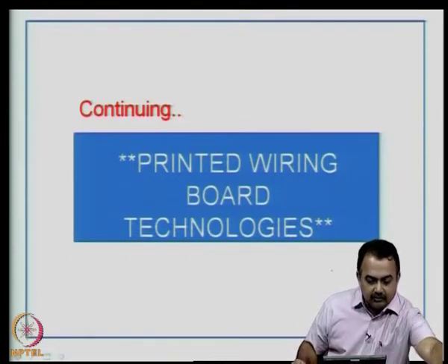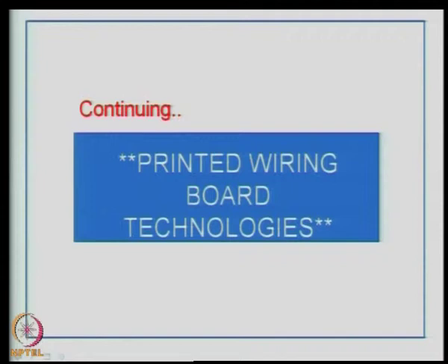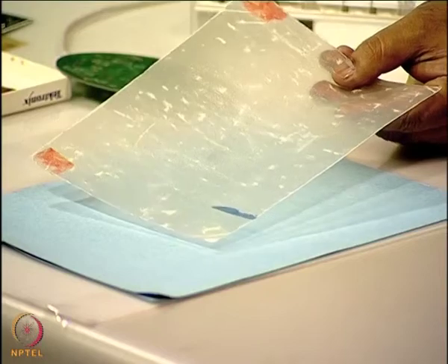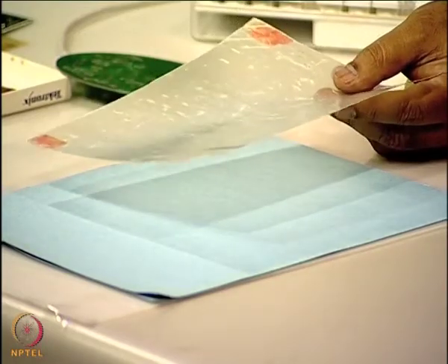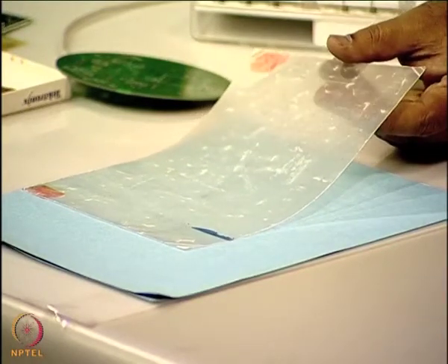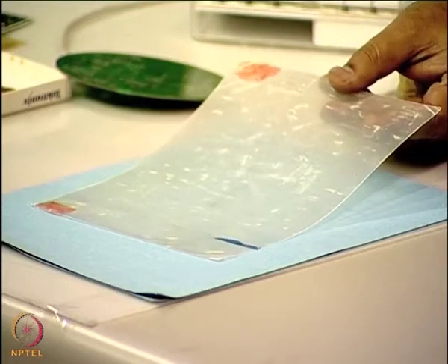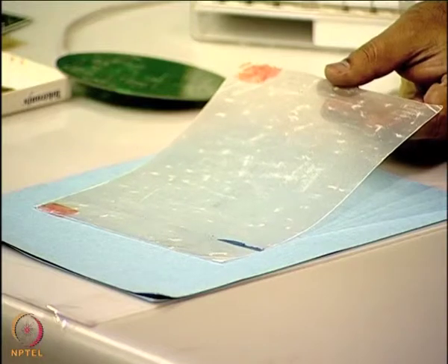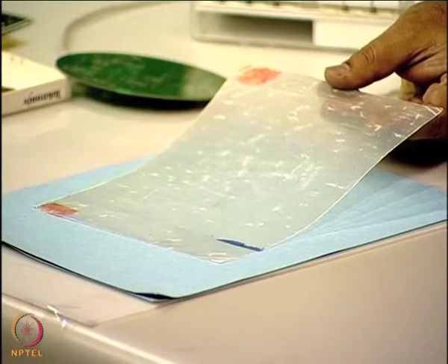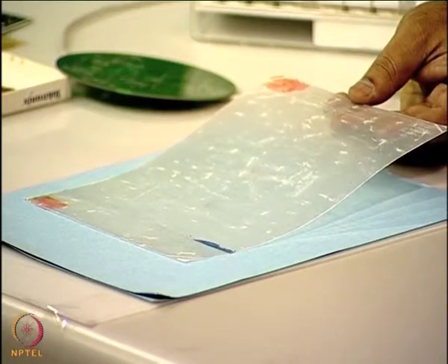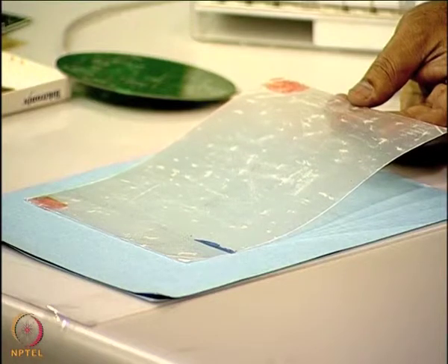The first thing that I would like to show you is basically a material here. As you can see, this is a pre-preg material. All of you know this is a dielectric material. There can be various organic resins that can be used to manufacture a pre-preg material. A pre-preg material is very important in the sense it gives the electrical characteristics to your system level printed wiring board, and it can have two components. Essentially, one is the organic resin and the other is the filler. Storage conditions are very important.